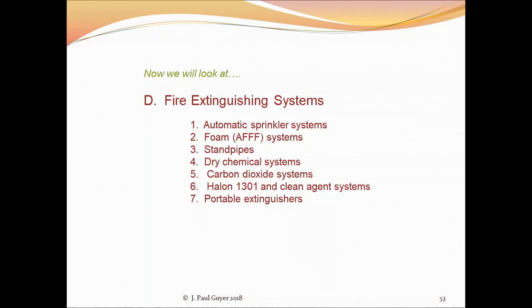You've got the exhaust fan sucking those greasy fumes out, and the grease accumulates in the exhaust system, catches on fire, and water is not something you can use to extinguish a grease fire. So dry chemicals of one form or another are automatically released into the duct system and the cooking surface to smother the fire.